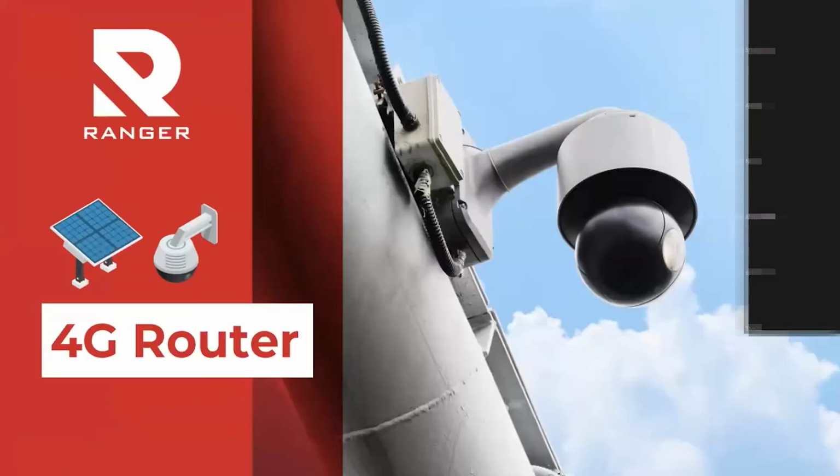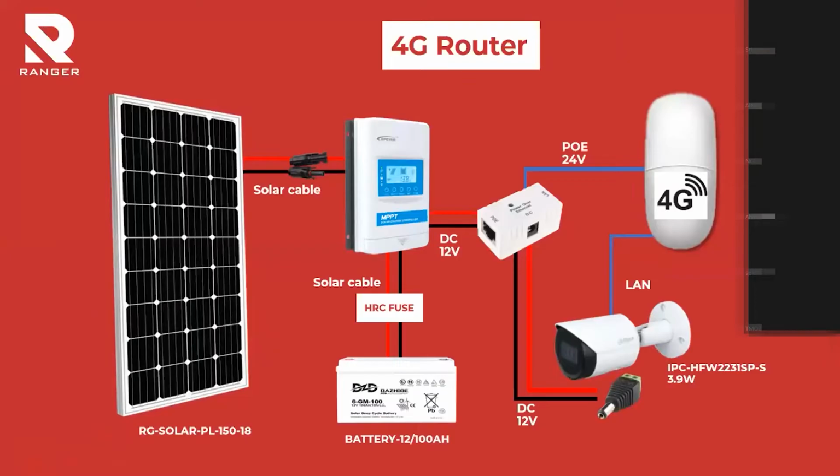Okay, next is the 4G router. The difference is, for example, if using one camera, just connect the LAN cable of the camera to the 4G router. This 4G router is normally powered by 24 volt PoE, same as the access point.